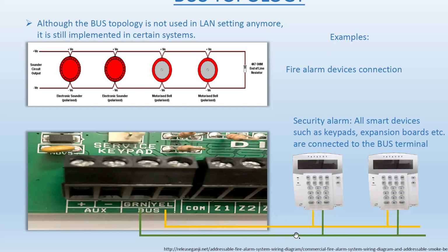Through different types of modulating of the signal, this device can individually communicate with the main panel, and this other device can individually communicate with the main panel, all at the same time, but they are on the same line, connected in parallel. Signal modulation, or frequency division multiplexing, is being used when it comes to that.